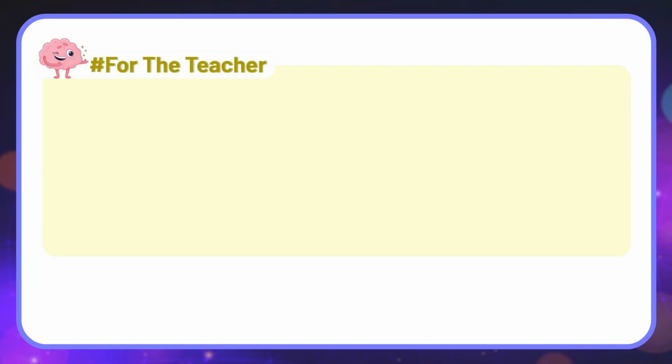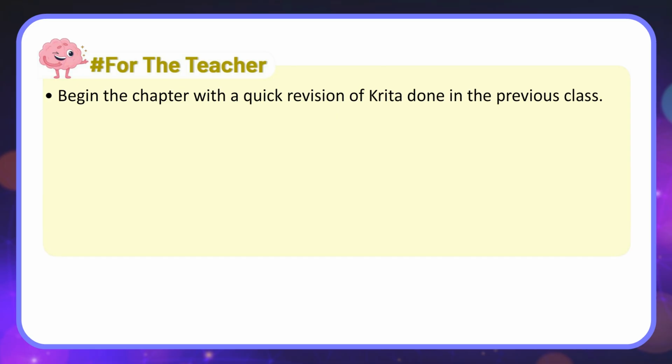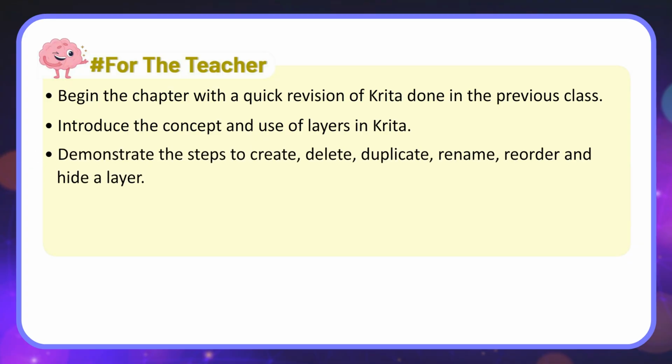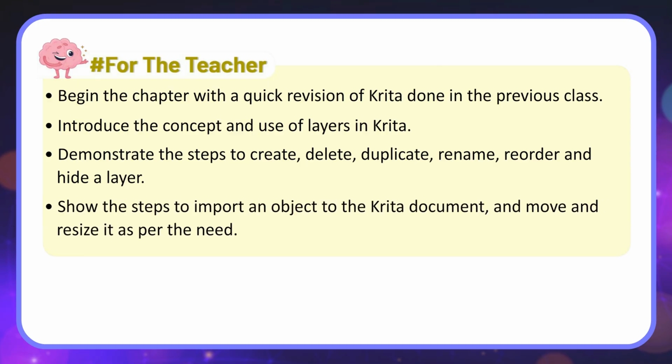For the teacher. Begin the chapter with a quick revision of Krita done in the previous class. Introduce the concept and use of layers in Krita. Demonstrate the steps to create, delete, duplicate, rename, reorder and hide a layer. Show the steps to import an object to the Krita document, and move and resize it as per the need.